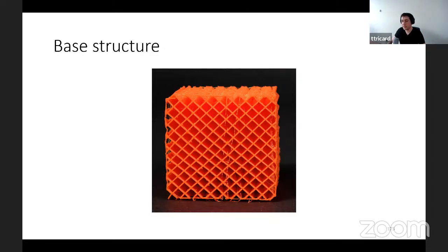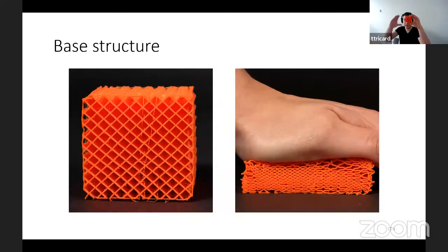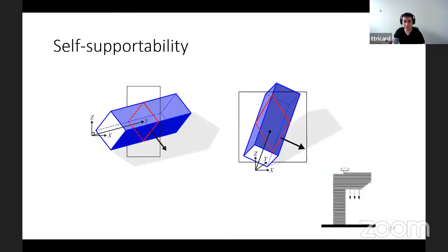It's fairly interesting because in 3D printing it will be fairly flexible, as you can see here, in one direction, in another one too, and in this one it won't be. So it gives you a strong anisotropic response. It was also very interesting because this structure can be oriented however you want in space, as long as you don't make it roll here.